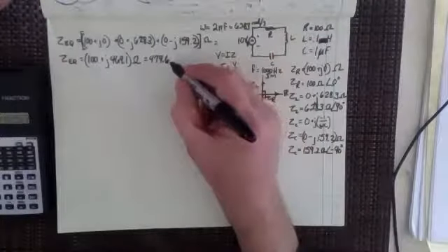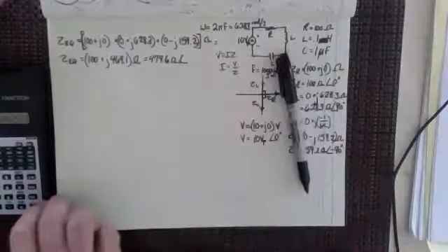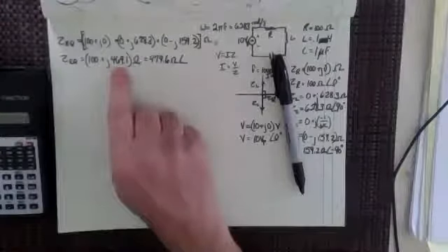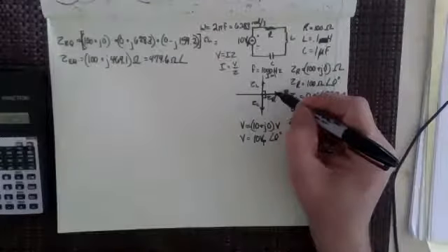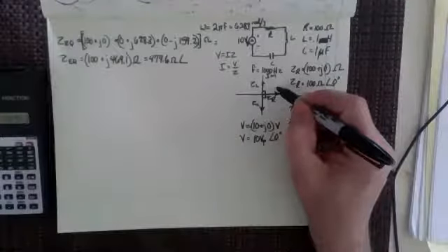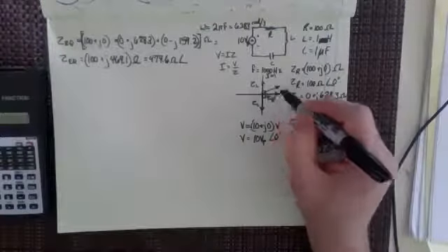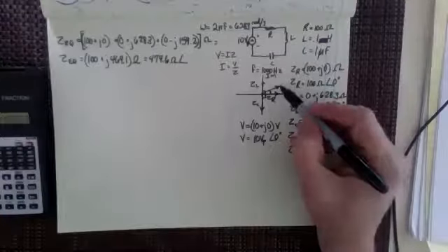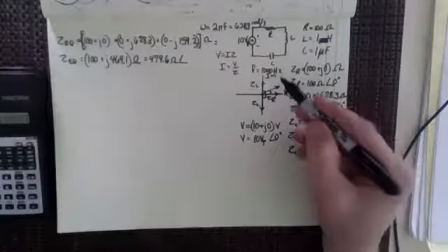So I've got 479 ohms, and what angle are they at? Well, remember how we figure out the angle. We take the inverse tangent, right? Because we've got 476, and then we've got like 100 up here, and so we're really looking at that phasor right there. We know the magnitude because we square both of those, add them together, and take the square root under Pythagoras' theorem.